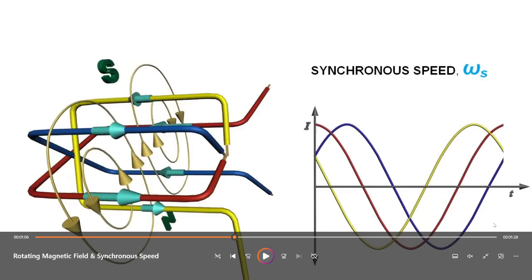If we do not place the windings mechanically at a 120 degree phase shift, the waveforms won't come at a 120 degree phase shift. Since we are placing the windings at a 120 degree phase shift, the currents will come at a 120 degree phase shift. That's 120, 240, and then 360 degrees.